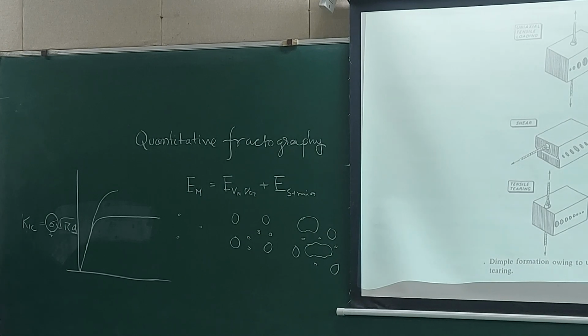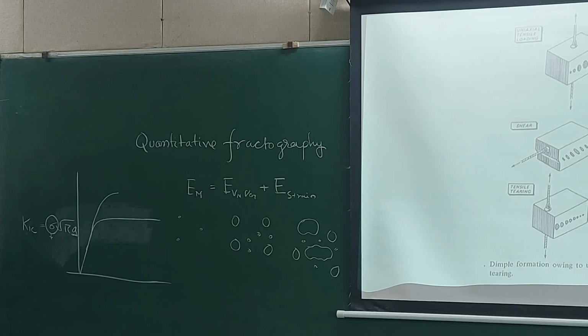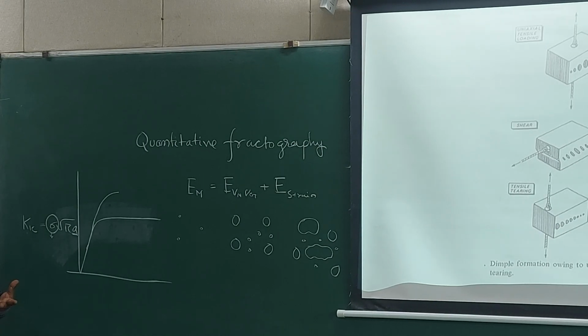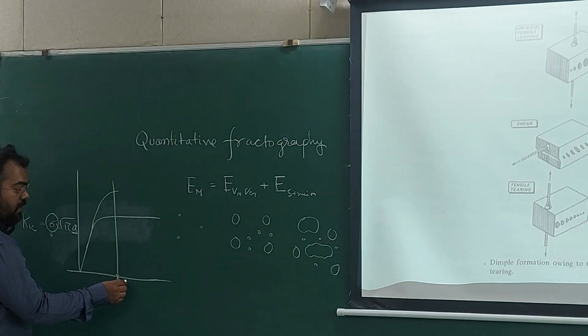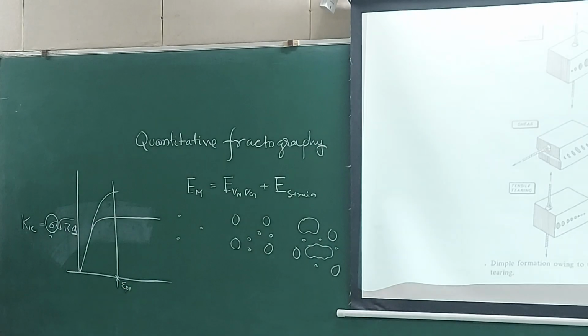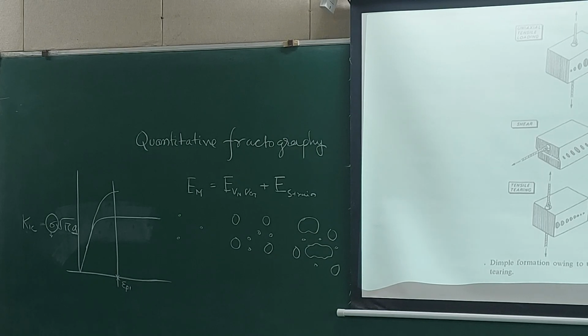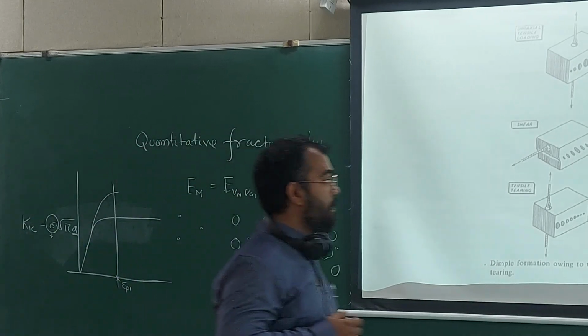It doesn't matter. If you look at the kinetics of damage, then what is defining nucleation rate? Let us take GTN. Nucleation rate is defined by how much von Mises stress is there and how much plastic strain rate is there. So the stress being higher will matter, but you have the same amount of plastic strain at that point. So that is also governed by the plastic strain, how much that is.